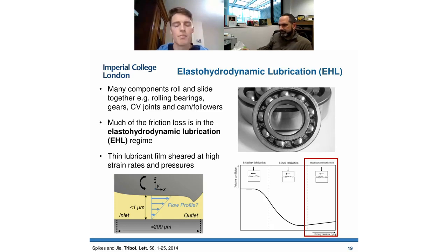All of the conditions I'm going to talk about are above the lambda ratio where surface roughness affects friction coefficients. So basically, there's no roughness effects on friction. It's just purely from shearing of the solid-like lubricant film.